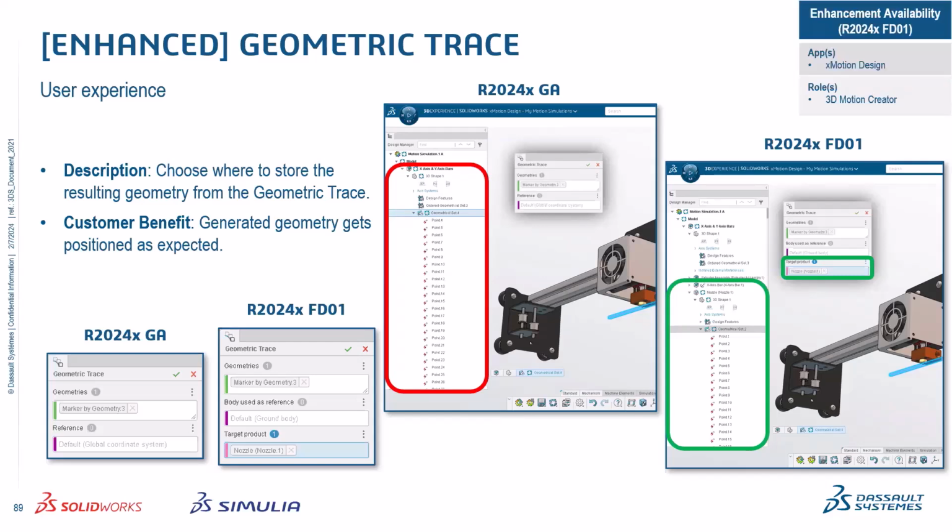Yeah, sure. So the CATIA Lattice Designer role is required to initially generate the lattice or change the actual structure, so going from like a honeycomb to a square structure and so on. So changing the actual lattice itself. On the X design side, you can do a simple solve and the lattice geometry will show inside of X design. And then you can also modify the size and modify like the pocket size that the lattice is filling to an extent. If you obviously change the dimensions too much, it's going to break the lattice and you're going to have to go back to Lattice Designer to regenerate it.